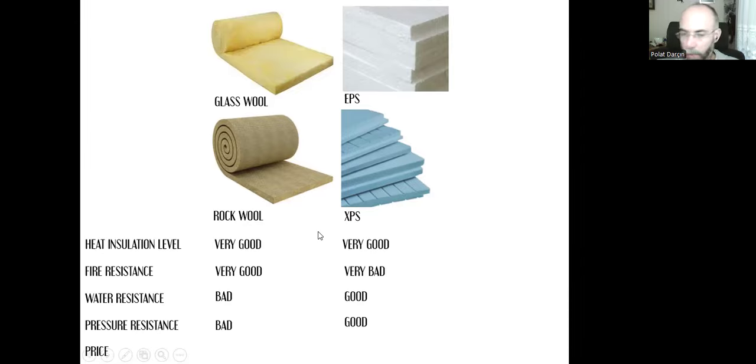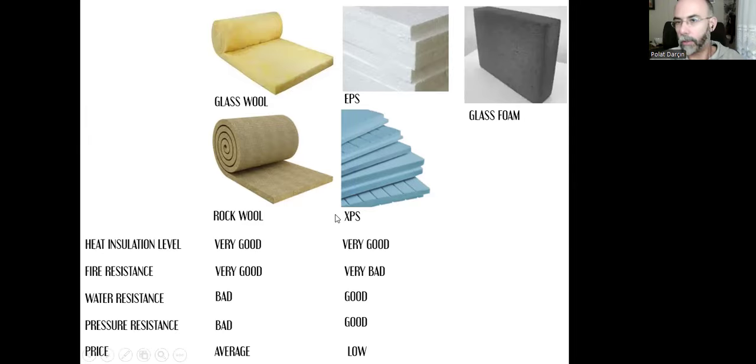And the price, let's compare the price. Glass wool and rock wool are higher than EPS and XPS. EPS and XPS are cheaper than glass wool and rock wool. And we have a third group. Again, it's made out of glass, and that's called glass foam.